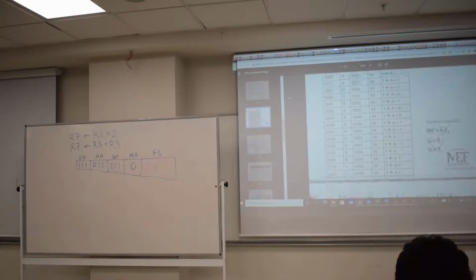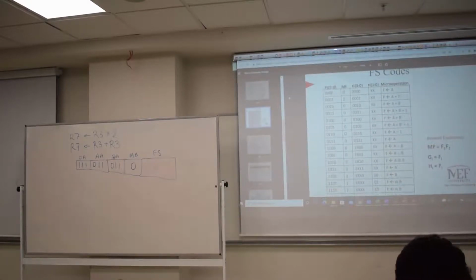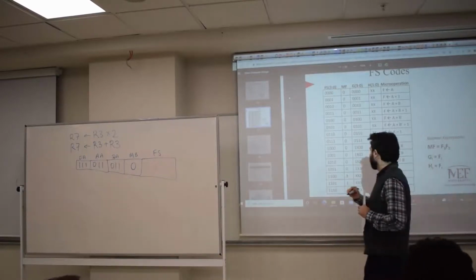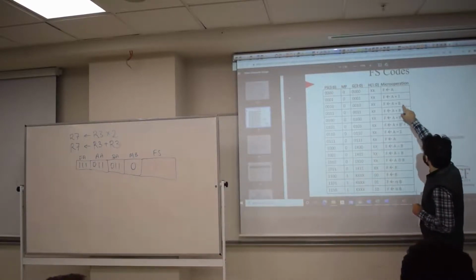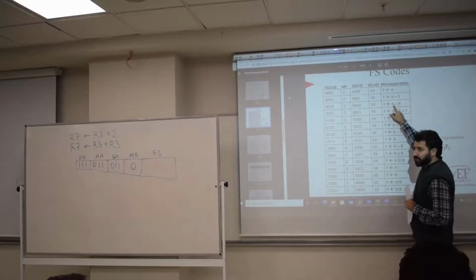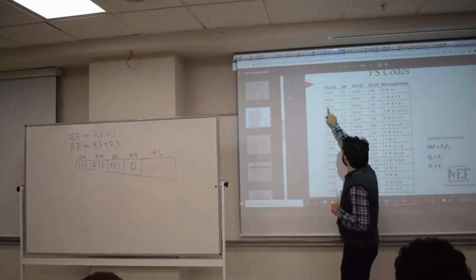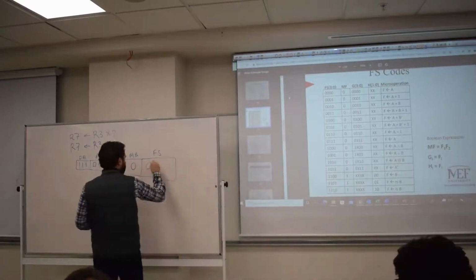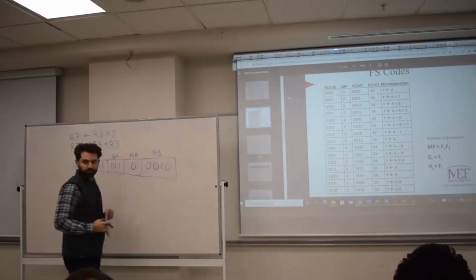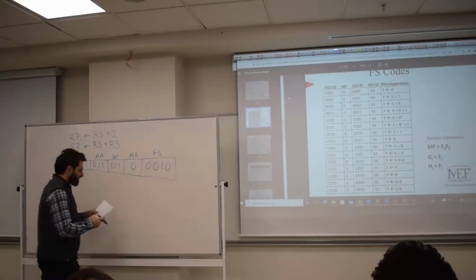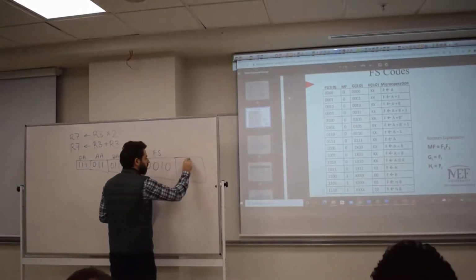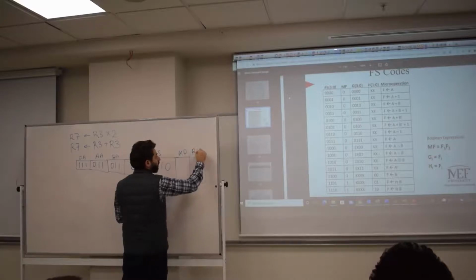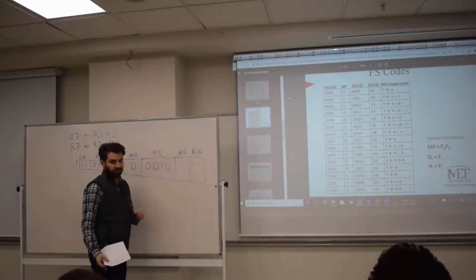All right? So you don't need to memorize anything, you see. I'm looking for what? The plus sign, addition, right? So I look at the addition, I figured it out. A plus B is here, which corresponds to 0, 0, 1, 0, function select equals 0, 0, 1, 0. That's my function select. There are 2 more bits. One is for MD and one for RW. I'll just read right for the register file.